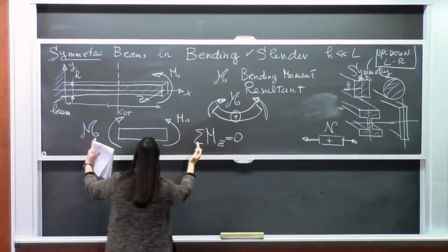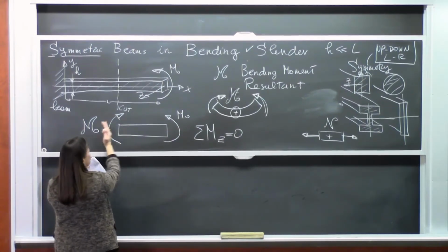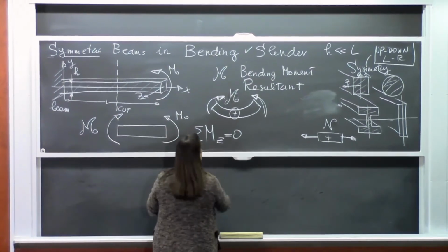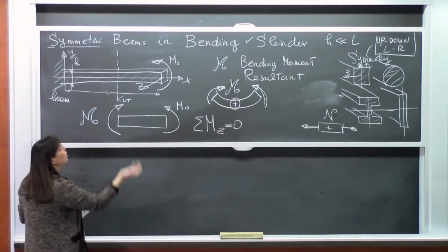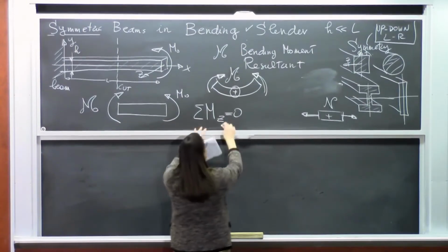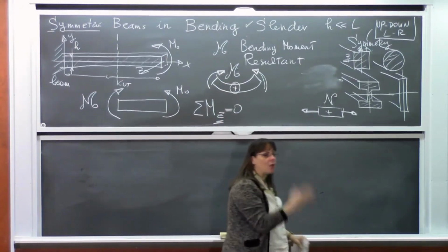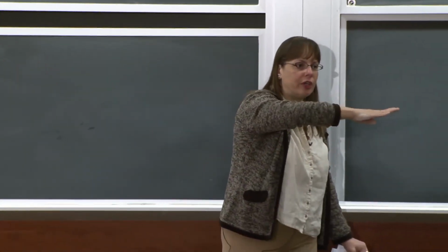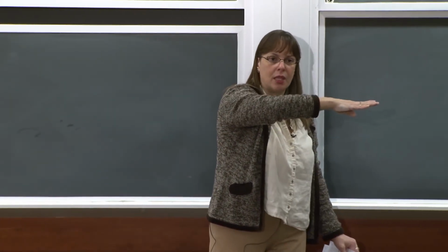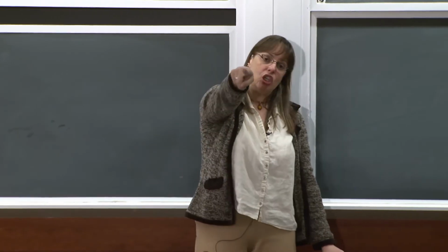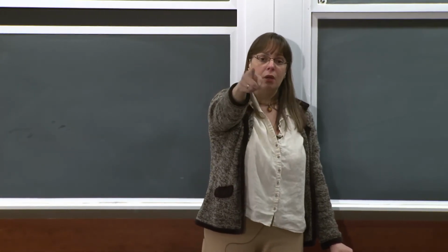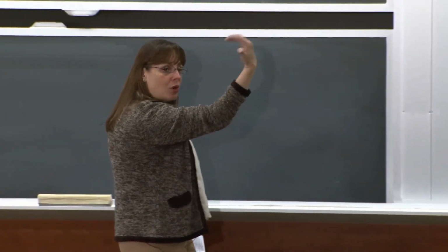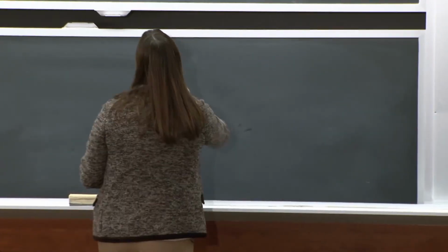So if I sum of the moments z equals 0, and I have only concentrated moments, I don't need to worry about the pivot. So now z, moment z, very important. See this guy z? The same way as when I sum the forces in x, I project all the forces in the x-axis, right? When I sum the moments in z, which is at you, I must sum the moments in the z-axis. So the positive z moments are counterclockwise.